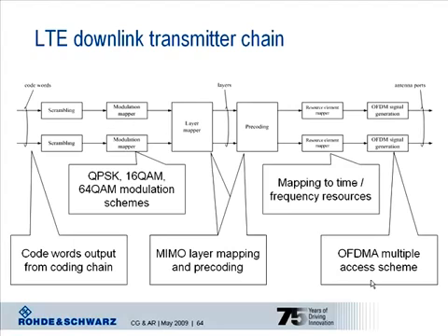You have different precoding types depending on the radio channel characteristics, for example. Then the resulting signal out of the MIMO precoder is mapped on the OFDM time frequency resources for transmission on each antenna port. And again, LTE supports up to 4 transmit antennas at the base stations. It could also be 2, for example, depending on whether it is 2x2 or 4x2 or 4x4 MIMO.